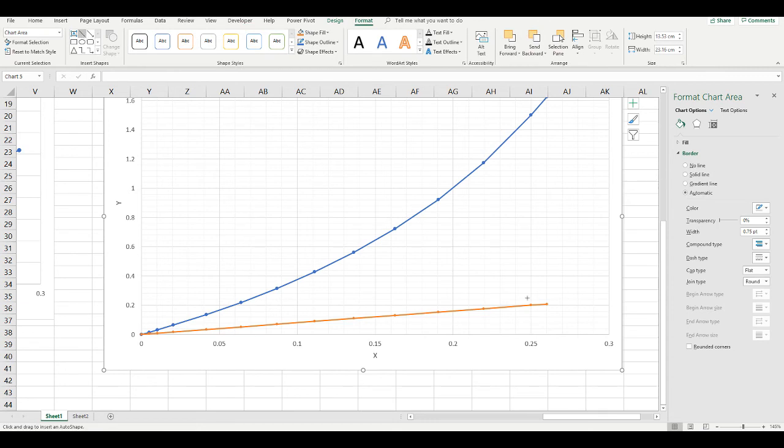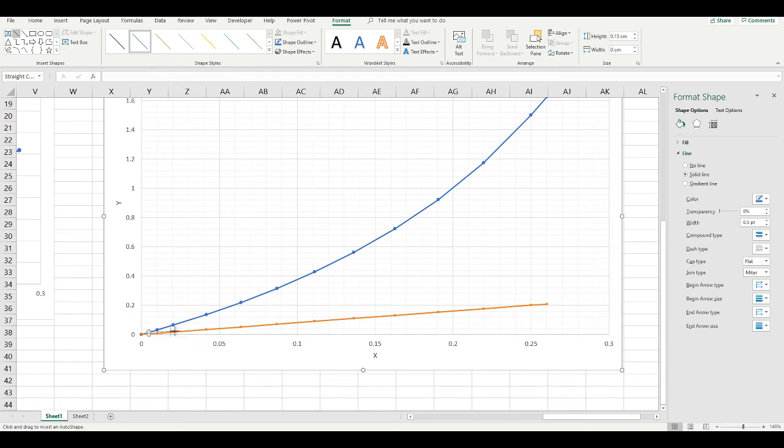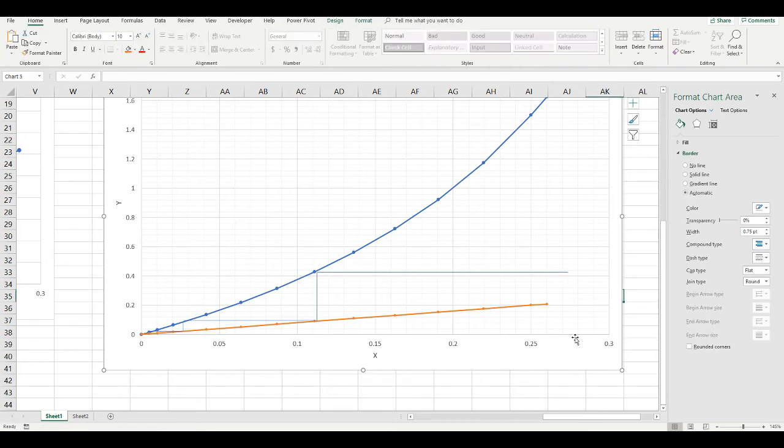We're going to trace our first equilibrium relationship, starting from the first point. So you can see that after we trace this, we only have 3 stages, and we're way above the operating line.